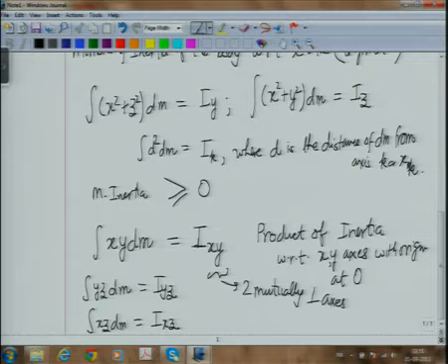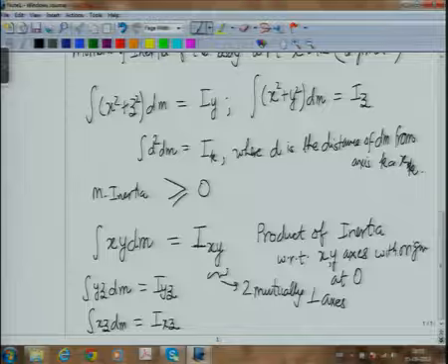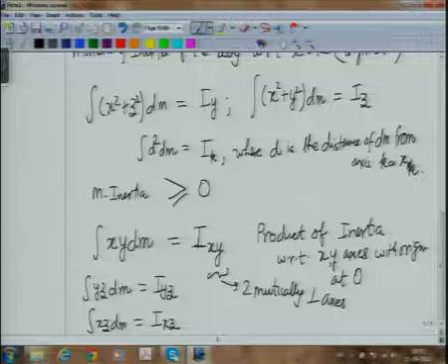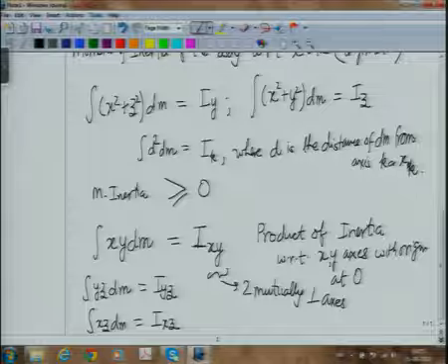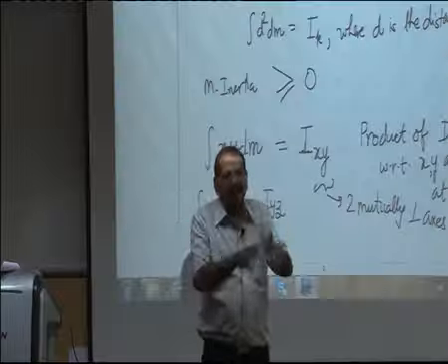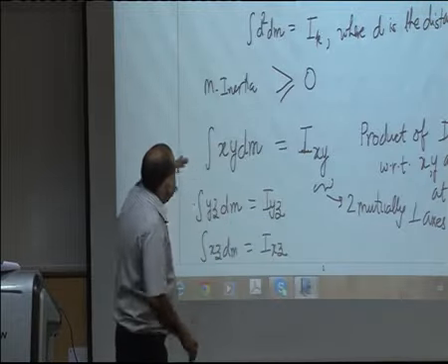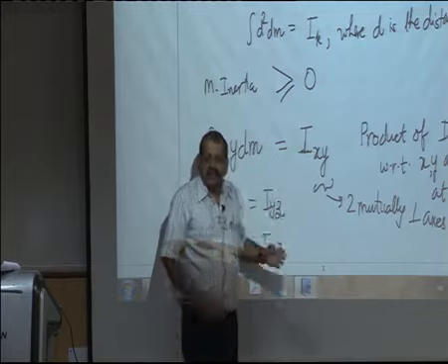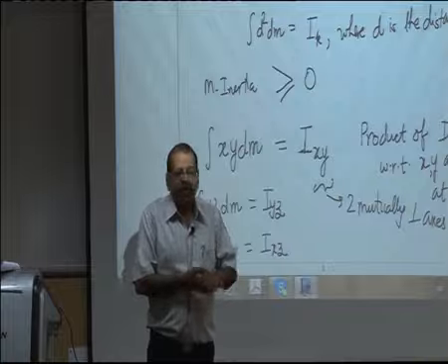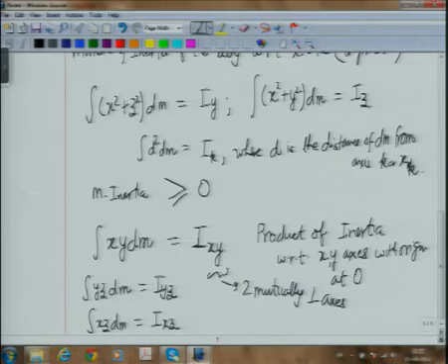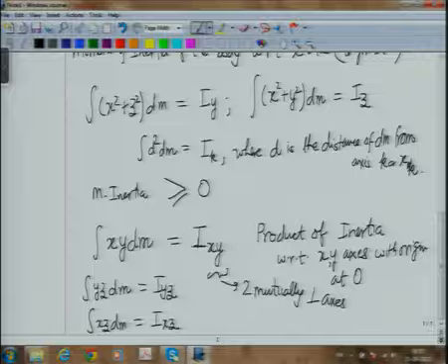Now why don't we see this for most common bodies? When we rotate this, we only see rotation about that axis, we don't see rotation about the second axis. So what common sense observation can you make out of this? That this quantity must be 0. And what we will learn, at least either by today or by the next lecture, is whether, at least by inspection, we can locate when these products of inertia will be 0, or how we find them. That is what we will be finding out eventually. So these are three things called products of inertia.